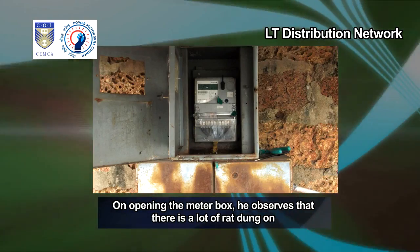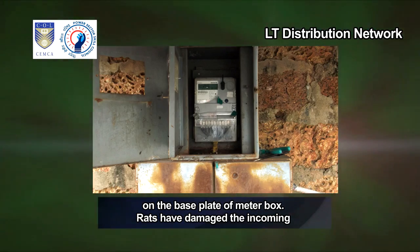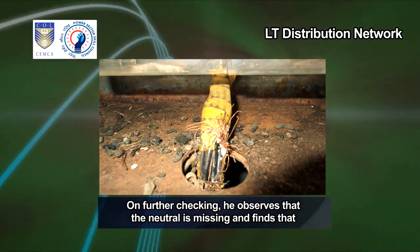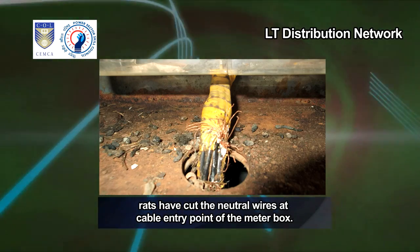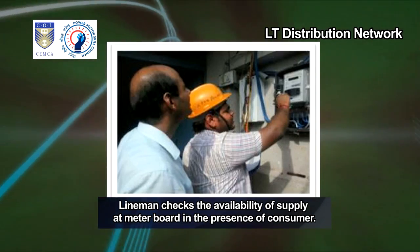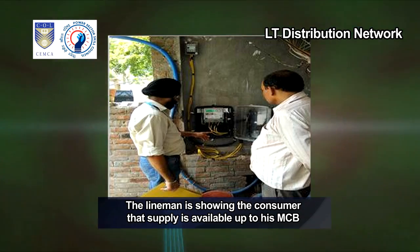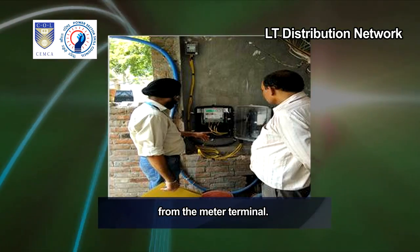On opening the meter box, he observes that there is a lot of rat dung on the base plate of the meter box. Rats have damaged the incoming control cable at the entry point. On further checking, he observes that the neutral is missing and finds that rats have cut the neutral wires at the cable entry point of the meter box. Lineman checks the availability of supply at the meter board in the presence of the consumer. The lineman is showing the consumer that supply is available up to his MCB from the meter terminal.